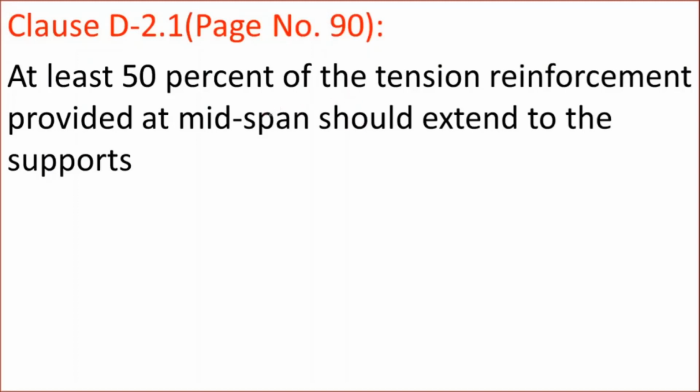Then next one: at least 50% of the tension reinforcement provided at midspan should extend to the supports. So these clauses are related to what? D2.1. At the starting itself I told that the clauses that start with D2 point are related to the simply supported slabs.